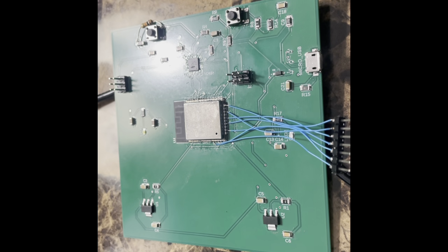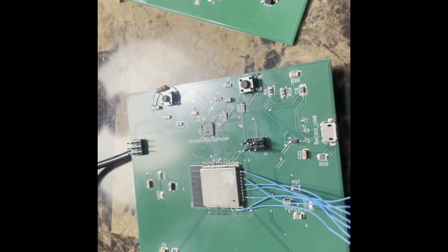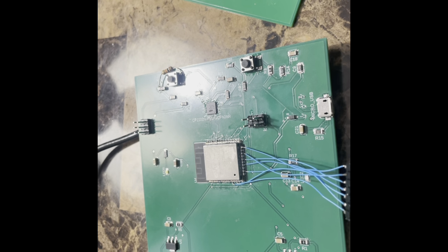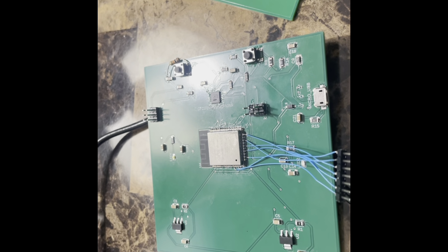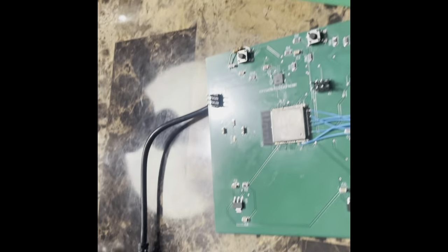Some of the changes that occurred on this PCB was we swapped out the switching regulator and we used another linear regulator because we knew those worked. And we also updated the circuit that we had issues with prior, and we made that correction, as we can see over here. So now we were able to effectively create a circuit that was wired correctly, and then we're able to boot up the chip.